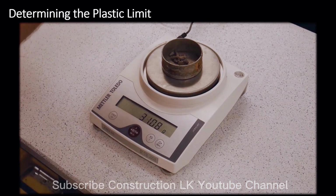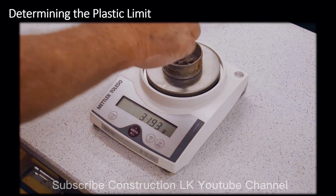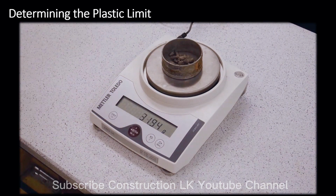The procedure should be repeated for another 2 grams portion of the soil from the original sample. This should be continued until the container has at least about 9 grams of soil. The same process should be repeated to obtain another container of at least 9 grams of soil. The moisture content from the 2 containers should be computed separately and the average value taken to determine the plastic limit of the soil. Note that this is a single point test. Therefore, no graph is needed to determine the plastic limit.